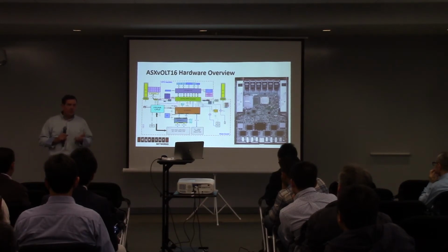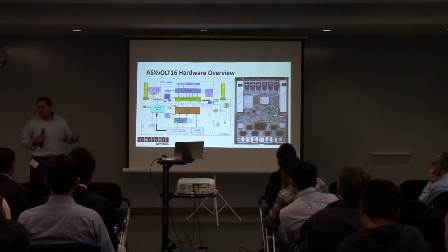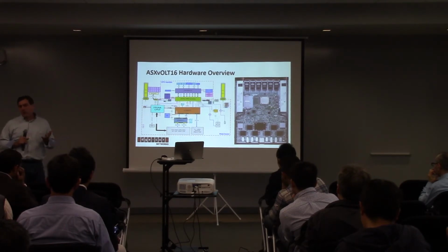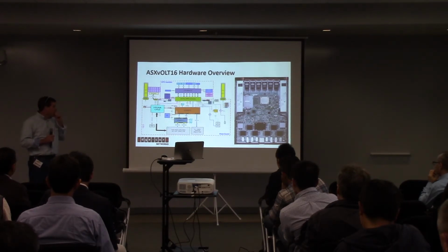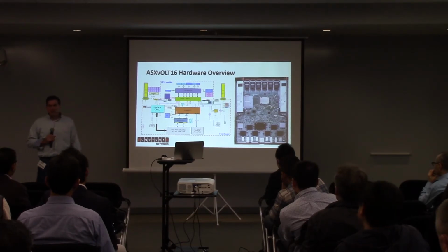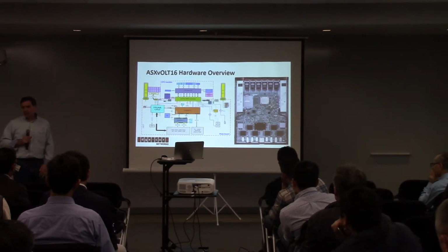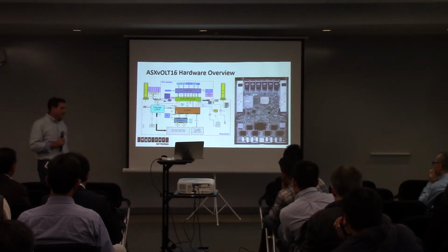It has great quality of service features. So even though in this design a lot of that PON traffic may just pass through that chip, and that's really used to aggregate that PON traffic up to the 100 gig links, there's plenty of functionality in the future that can be exposed in this piece of switching silicon if that's desired. Okay? And the other things in the heat sinks are CPLDs and FPGAs to run the low-level optics and communication paths in the design. Okay?